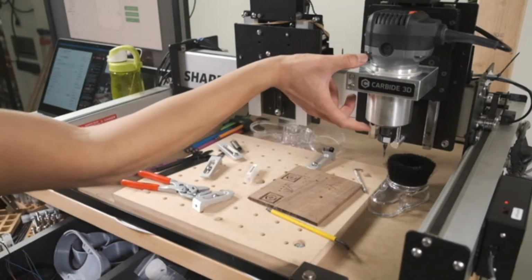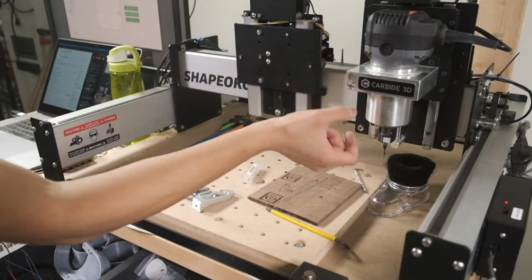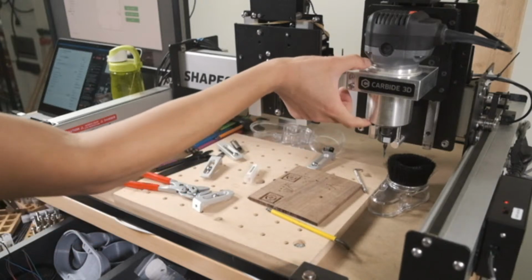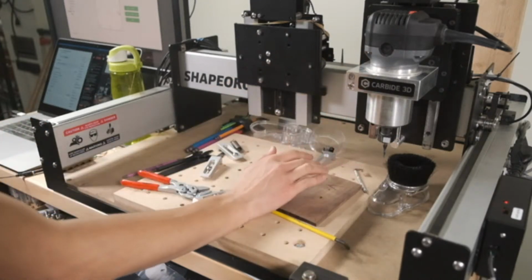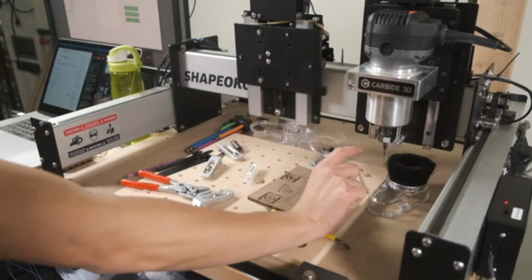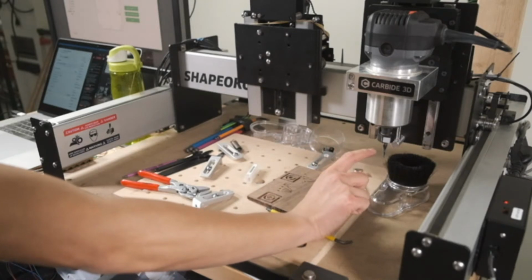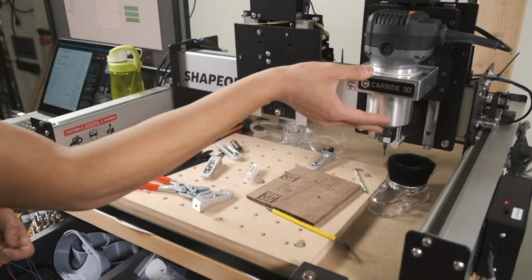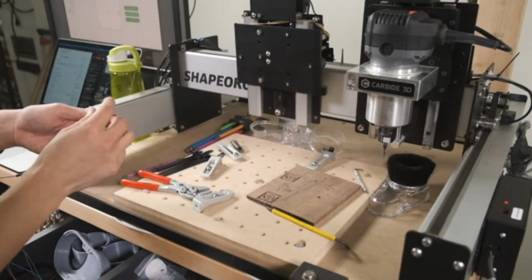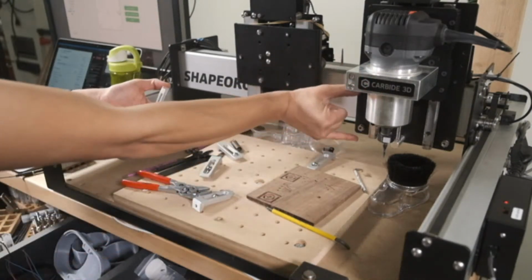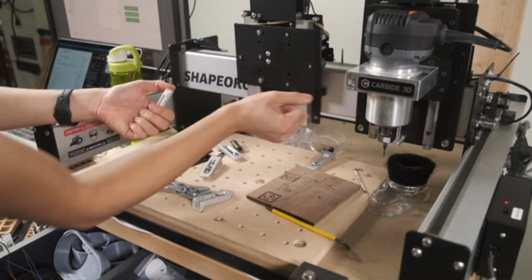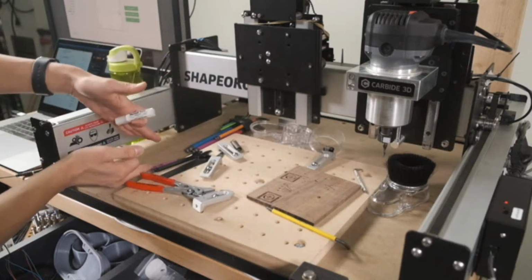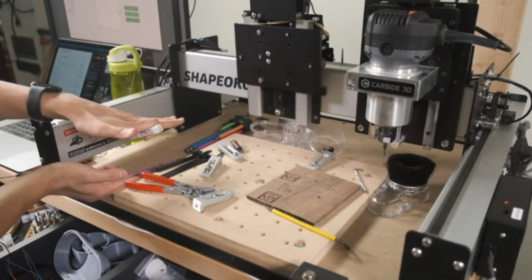You can adjust to a point where the spindle is in the mount, and that can help you get a lower cut. Or if you're using a really long tool and you're having trouble clearing your features, you can actually slide the router up. So that's one way you can work around the restrictions of your 3.5-ish inches of Z travel to make the most of your 3+-ish inches of clearance.